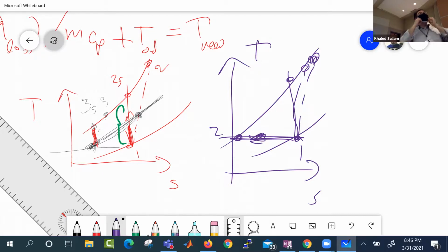Say that again. So, the compression itself is not isothermal if you put it in a vacuum. You are also thinking, I want it to be adiabatic, like perfect adiabatic. Isothermal is not really adiabatic. You have to do it really, really slowly, so that the heat transfer has a chance to cool you, right? But they didn't go that route. So isothermal does not mean adiabatic. Isothermal does not mean perfect insulation. It's the opposite. You want all the heating to leave.